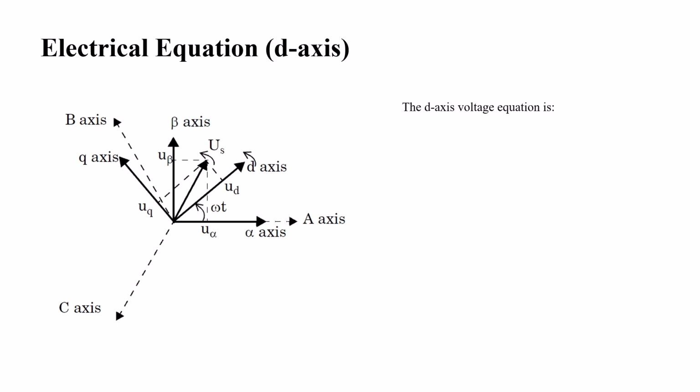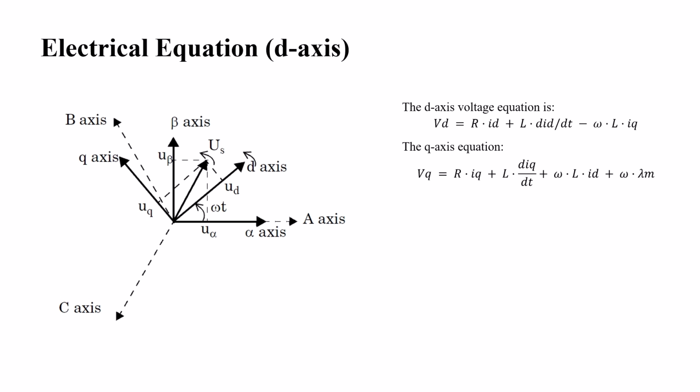So that's why. The d-axis voltage equation, if we are deriving that one, it will be related to the resistance and inductance of the d-axis, and also the angular position of the total system or the motor. And in the same way for the q axis, we have the same, but with respect to inertia and everything also coming into consideration. So that's why we need to consider the q axis, which needs to be reduced to, or maintained at, zero. Then only we can get very precise control.